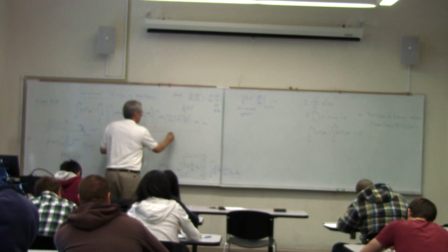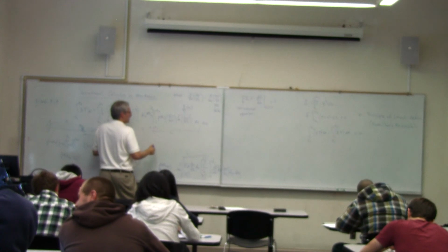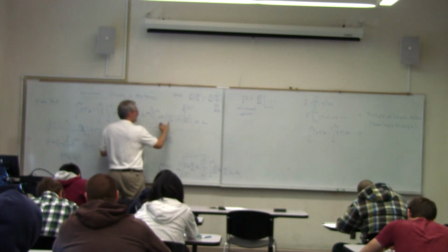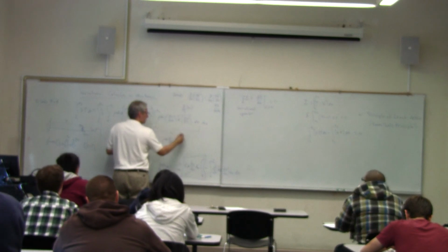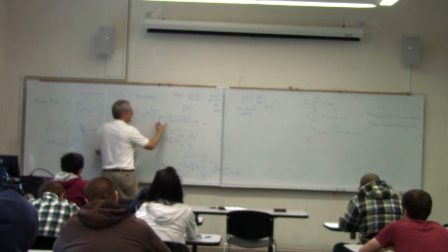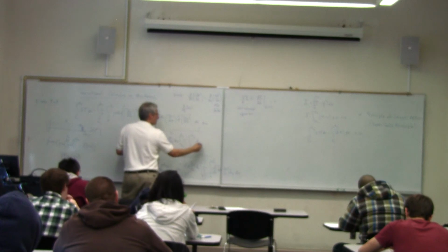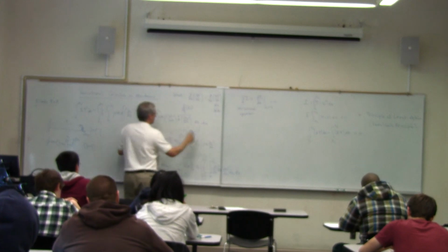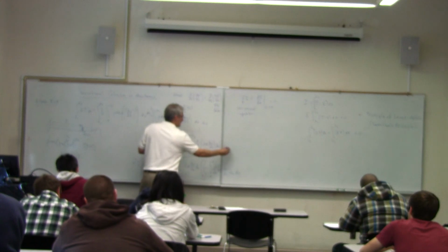And if we integrate this by parts, again with the integral over x on the outside, this is going to be rho a partial u partial t, this times this, delta u evaluated from t1 to t2, minus the integral from t1 to t2 of, now we're going to transfer the derivative with respect to time over to here, partial with respect to t, rho a partial u partial t, times delta u dt.